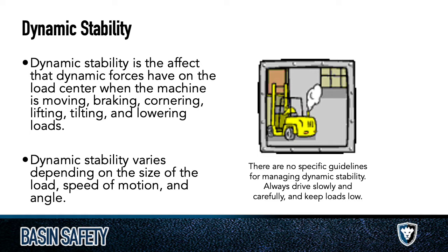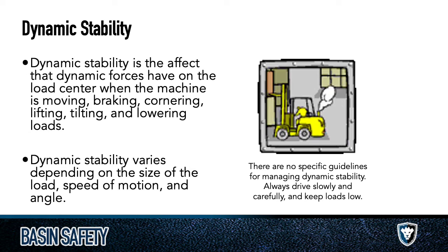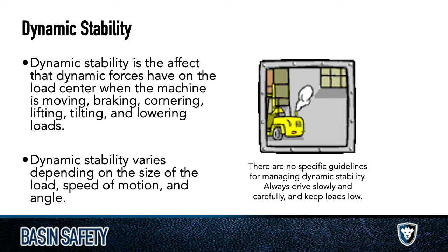So your dynamic stability, again, along with the lateral and the longitudinal stability, all come into play. As you're moving the load, your center of gravity is going to shift with your inertia. And as you make quick turns or maneuver, it's going to shift. And if the load's center of gravity shifts against your vehicle center of gravity and is overcome, it'll tip over. People do die in forklifts every year. Typically, first of all, they don't have their seatbelt buckled, so they fall out of it, and then the forklift falls on top of them.